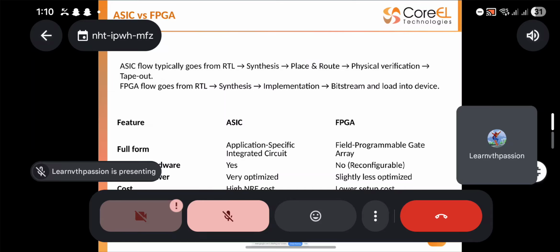Once the bitstream generation is successful, you will load it into the hardware and verify. For example, if you take counter code, there will be 4 LEDs. You will do the constraining for the 4 LEDs, and you will use 2 switches for reset and up/down, and you will run the up-down counter, where you will get the output on the LEDs.